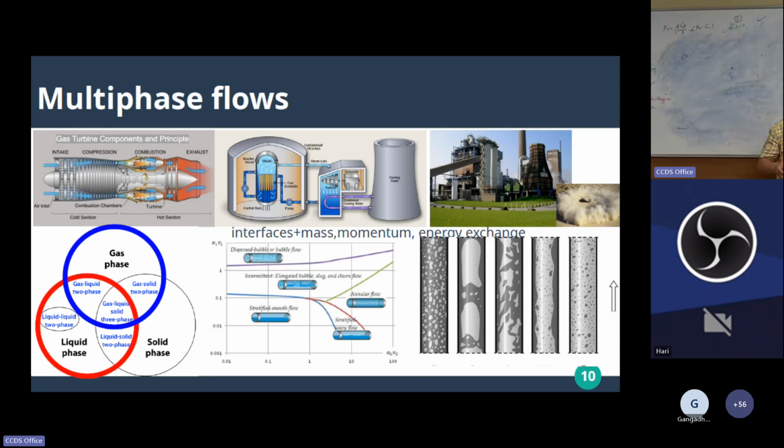So taking one single multi-phase flow solver for my entrance conditions is not the correct choice. Based on the entrance velocities, the liquid fractions coming in, and the gaseous fractions coming in, within the columns, tubes and other things, you may have to switch to multiple different solvers.